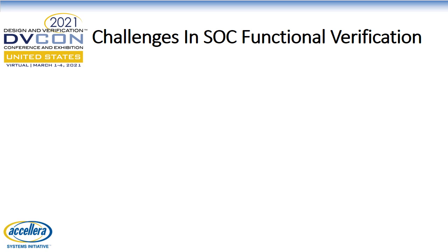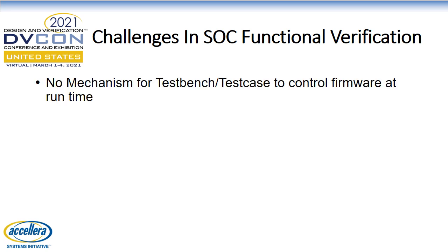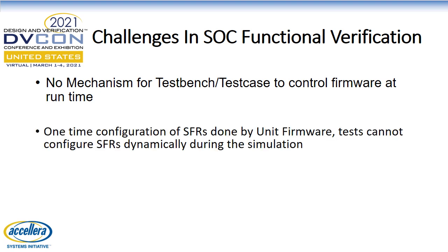So let me quickly discuss some of the SOC verification challenges we face in any traditional SOC verification approach, which we have tried to overcome in our proposed solution approach. First, there is no mechanism for a testbench test case to control firmware at runtime, as firmware is compiled statically and loaded into processor memory, so no interaction is possible between testbench and firmware at runtime.